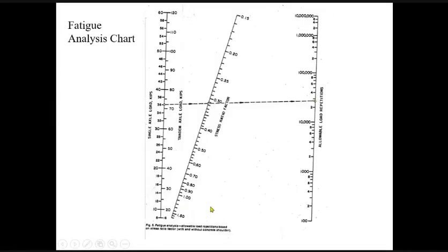So say for 10, this is a single axle, and if I have to find for tandem axle, I use this side of the figure. So for the single axle, I will use this side of the figure, and for tandem axle, I will use this side. So say for 18, and I have a stress factor of say 0.38, I'll join it and extend it. So here I will get this 10 million ESALs value. For say 30, I will get this 10,000.